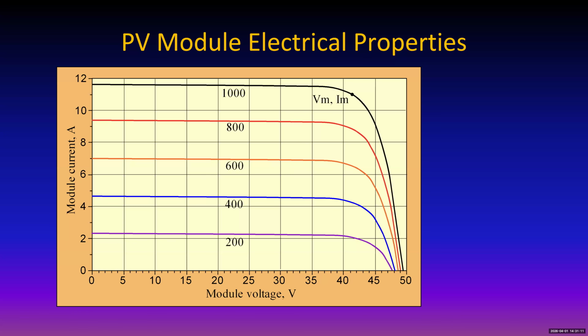So if you've got a module that has leads on it and they're not connected to anything, and you point it toward the sun and you connect your voltmeter across it and measure the DC voltage, you will measure the open circuit voltage. 25 years ago, this was commonly done by the field installers because the uniformity from module to module was usually within about 10%. Uniformity these days is less than almost 1%. So nobody worries about that anymore.